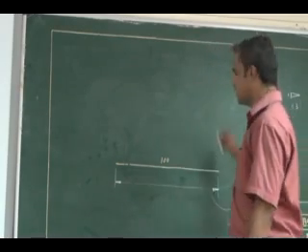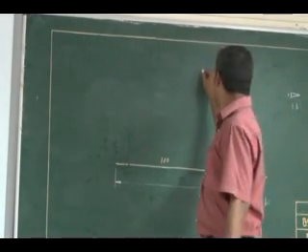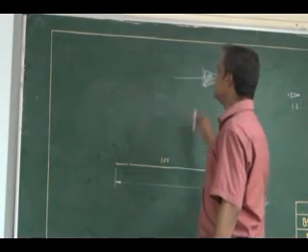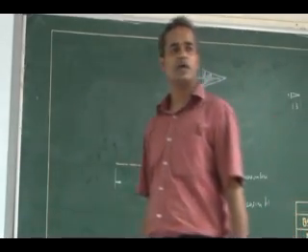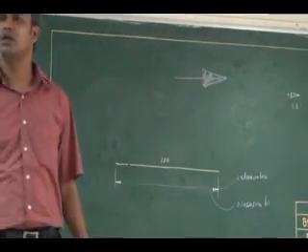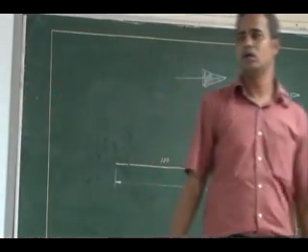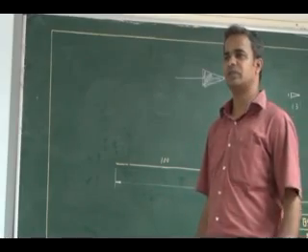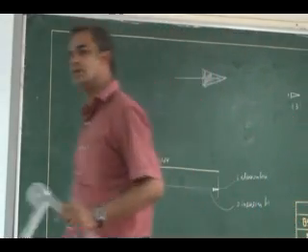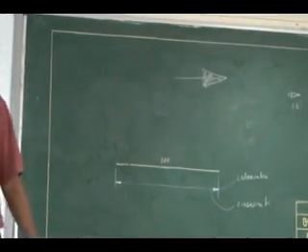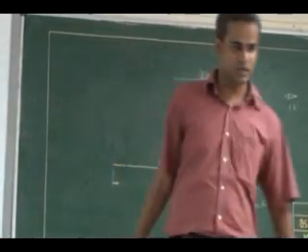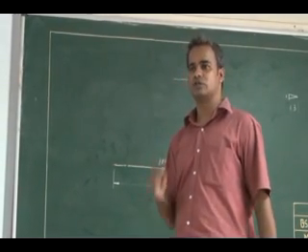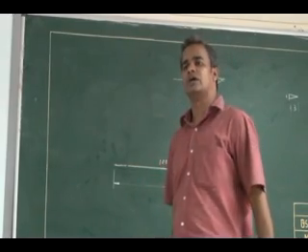You should not draw the arrowheads like this, very big ones, and shade them. If I see that in my drawing, how will my drawing look? So present the arrowheads neatly. It's very much essential. In the practice session I will correct your arrowheads, but now itself try to draw a neat, small arrowhead. At the same time you should have a 1:3 ratio.